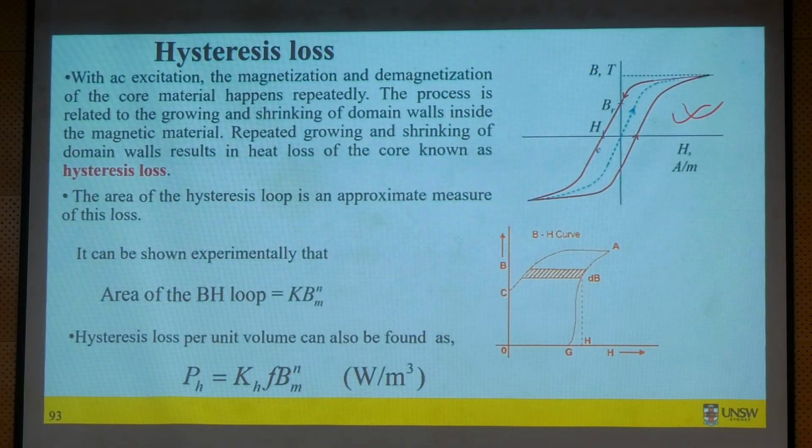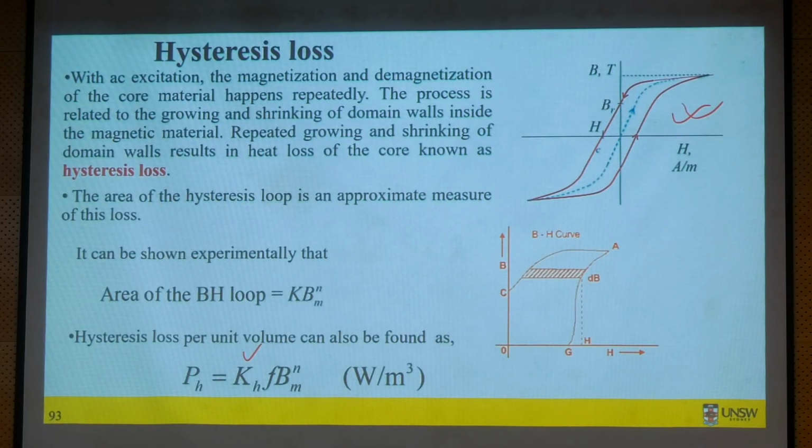And even if you somehow can separate iron loss from mechanical loss, separating eddy current from hysteresis is also not so easy. Okay, you can do it. There are some ways of estimating the KH and KE from measuring the losses for various operating conditions. So it's possible, but it's not accurate.